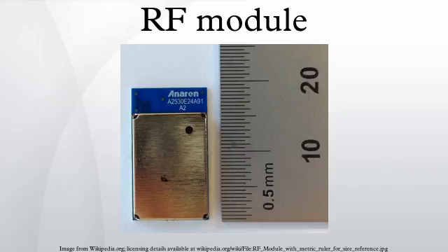Main factors affecting RF module performance. As with any other RF device, the performance of an RF module will depend on a number of factors. For example, by increasing the transmitter power, a larger communication distance will be achieved. However, this will also result in a higher electrical power drain on the transmitter device, which will cause shorter operating life for battery-powered devices. Also, using a higher transmit power will make the system more prone to interference with other RF devices, and may in fact possibly cause the device to become illegal depending on the jurisdiction.